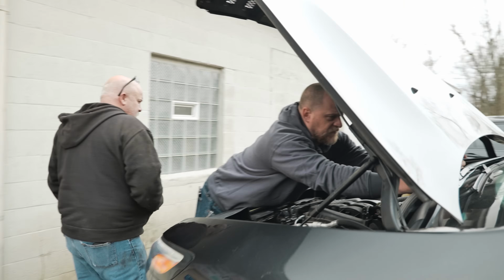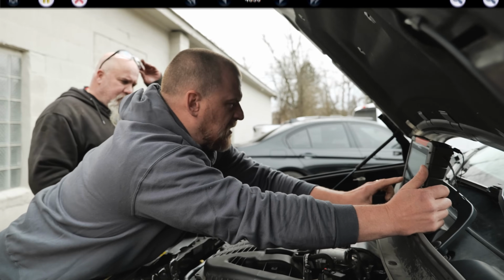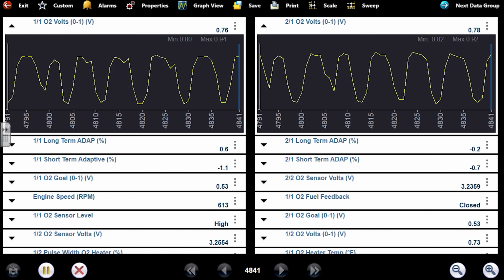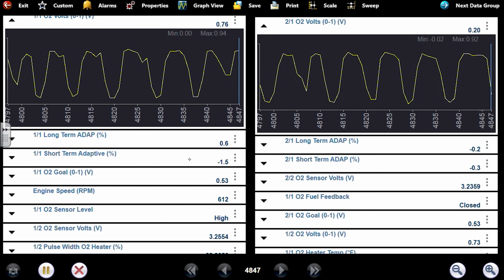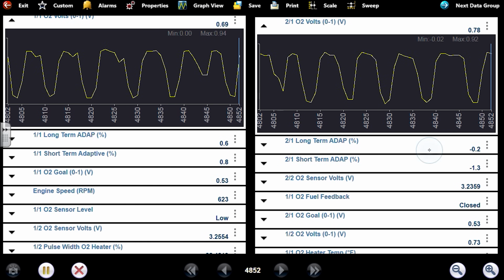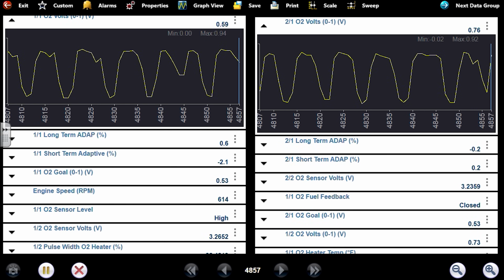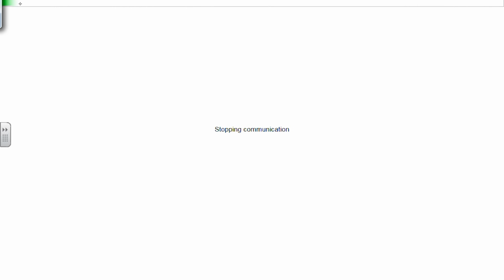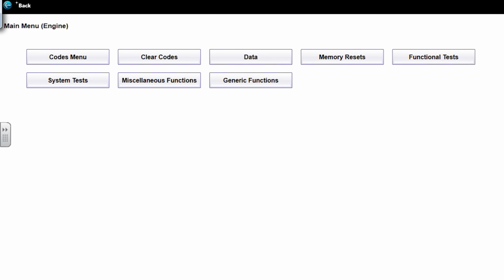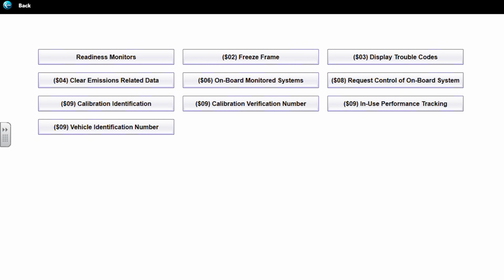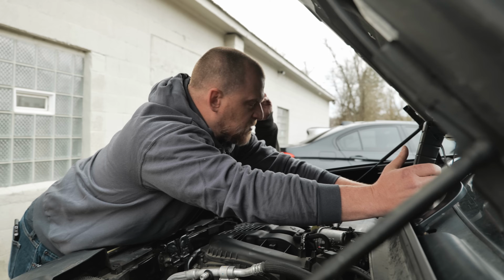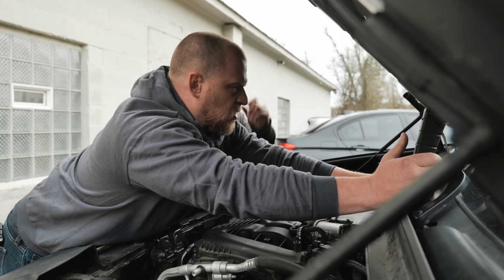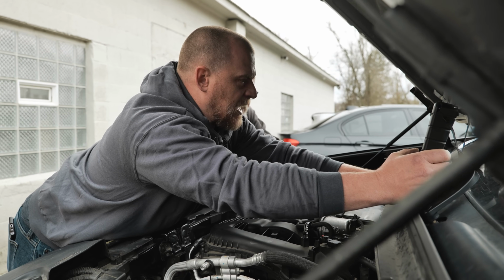If you look here, I'll show you the freeze frame data one last time, but look how nice these numbers look right now. There's bank 1, looks perfect. Bank 2 is the one setting the fault codes. It looks perfect too, right? O2s are moving up and down like they should be, but look at this freeze frame data. Just to show you what we're dealing with when this acted up. The engine was hot, it was being driven, they drove it for about 12 minutes on this data capture.